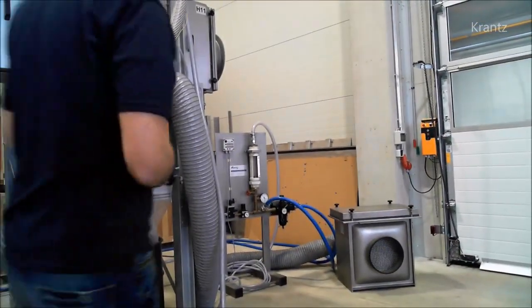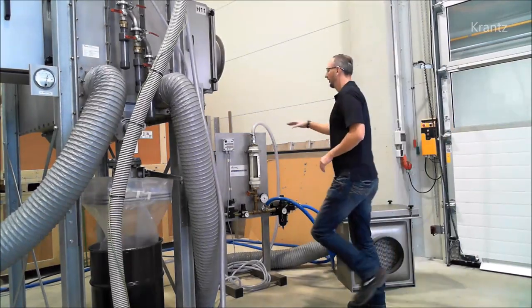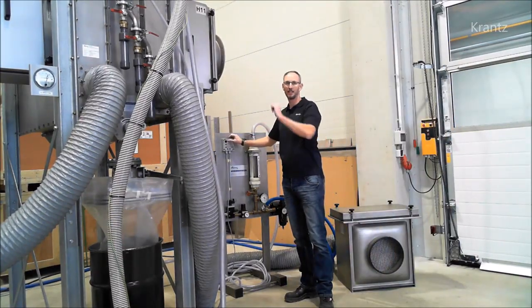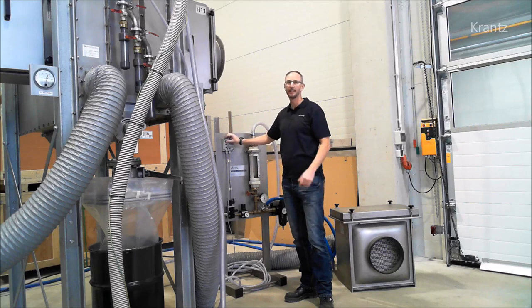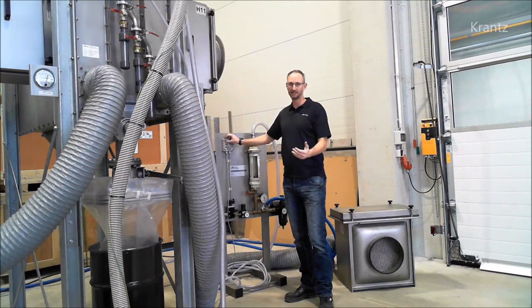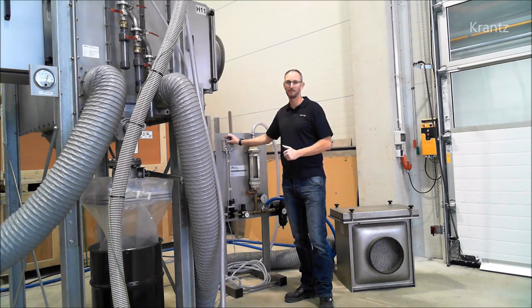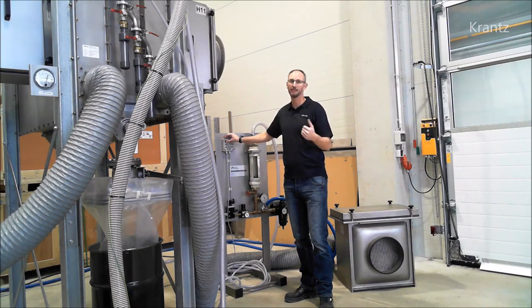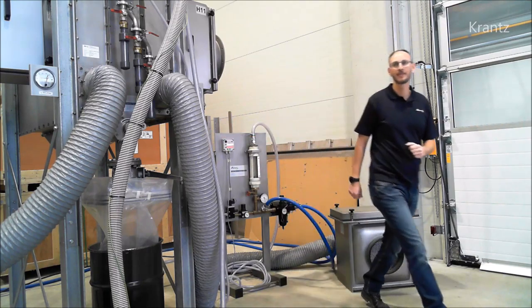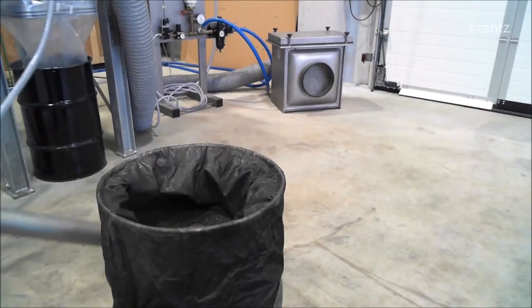So here we have the control system for the vibrator, which is located on the filter housing, and when I switch this on, it will vibrate for 10 seconds at the beginning. Then we have a 2-minute pause during the filling, and then 10 seconds vibrating. During this process, which goes on continuously, we will still fill the carbon. So I will switch it on now, then we have 10 seconds of high noise, and then we will show you the filling procedure. So those were the 10 seconds.